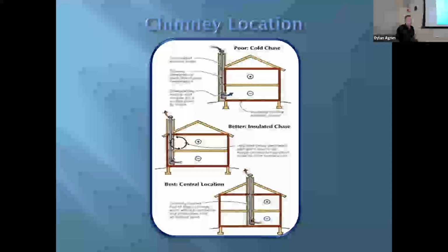Because if it's all the same temperature as the house, it's much more likely to draw properly. And you now have all that thermal mass inside the house, so it will trap the heat and transfer the heat inside the house. Whenever we have an opportunity to bring these chases or chimneys inside, they're going to work much, much better.